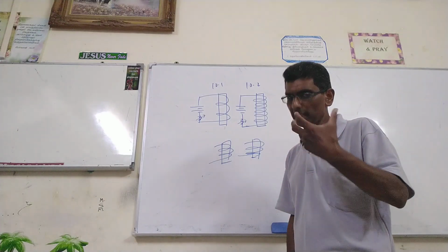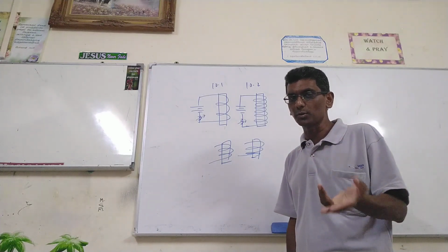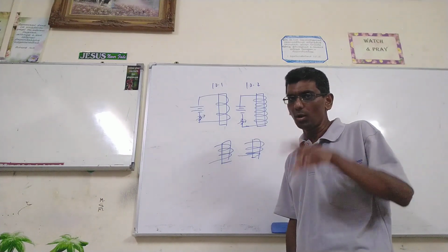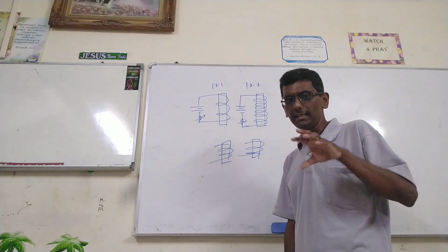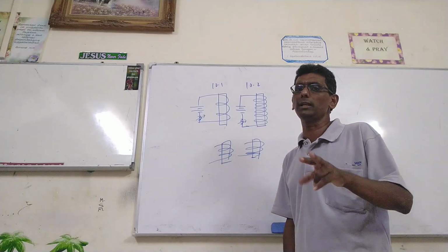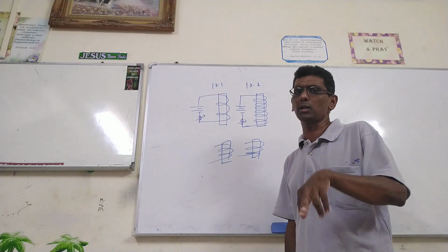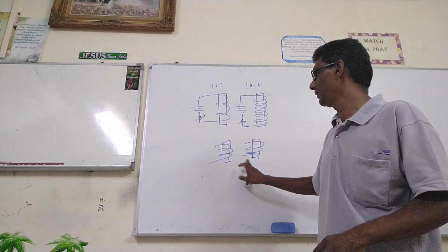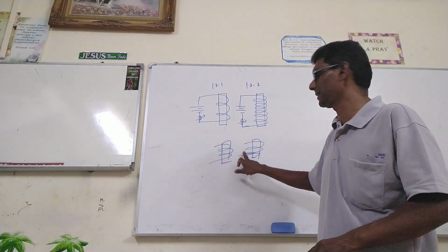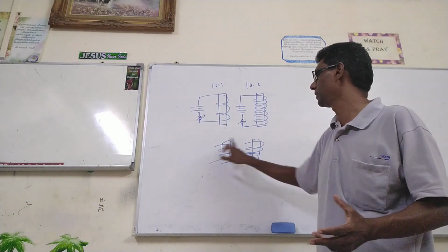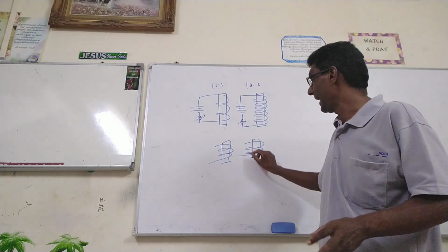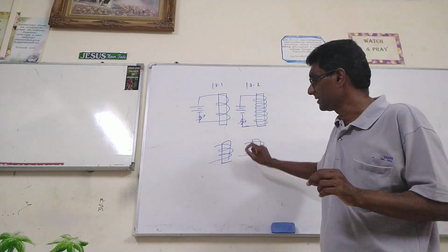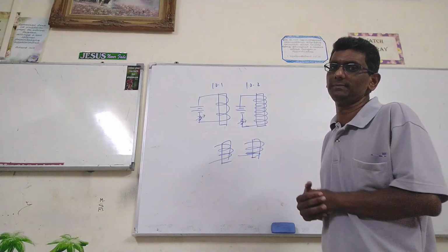Number of batteries can also increase the current, but more batteries also increase the voltage. Voltage must be fixed. Otherwise two things are manipulated: the voltage will increase and the current also increases. So instead, they fix the voltage with the number of batteries, say 2 batteries, so the voltage is fixed at 3 volts, and adjust the rheostat to increase or decrease the current.